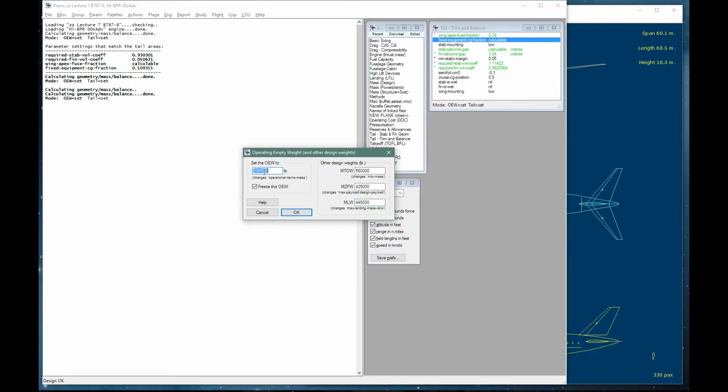Individual known values for OEW seem to vary between, say, 299,000 pounds and 306,000 pounds. So I will nominally set an OEW of 300,000 pounds exactly, for convenience, and because this also happens to line up with the start of the payload range diagram that is given in the March 2018 ACAP.